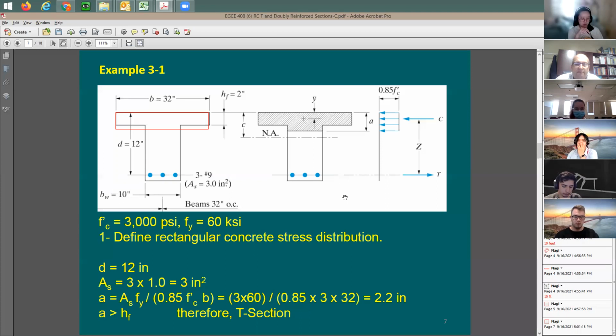This is wrong. Why? Because this cross-sectional area, the actual one, is not really equal to 32 by 2.2. This equation here implies that I'm gonna have a compression area of 2.2 multiplied by 32. Let me show you this equation here. I'm gonna type the same equation again, but just do a small trick. If this is true that the exposed area to compression is 2.2 times 32 inches, how much is this? I'm gonna call this area of the concrete.